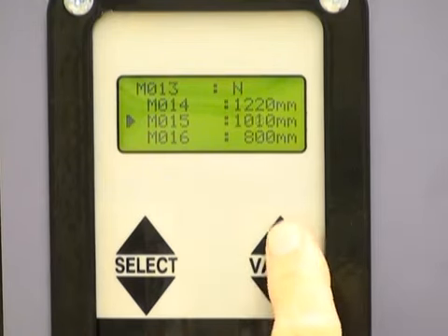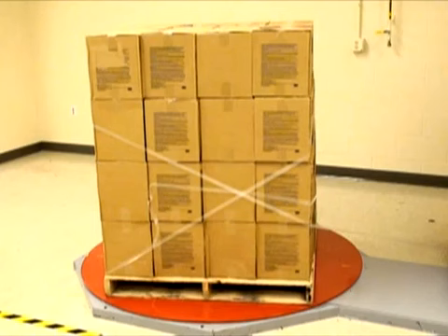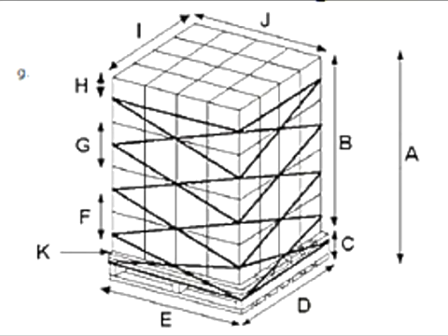These values change in preset increments. You should select program dimensions that most closely match your pallet dimensions. If the load dimensions are smaller than the pallet, use the dimensions of the load in place of the pallet for optimum wrapping.